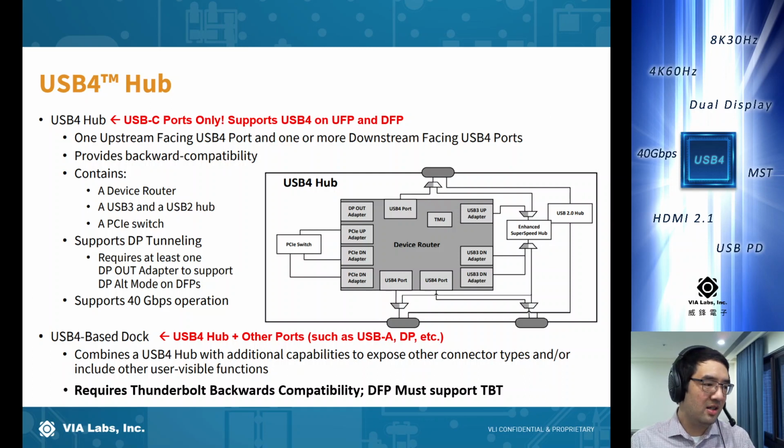Although dock may be kind of a colloquial term and it's been in use for maybe the last 10 years or more, when we're talking about it in relation to USB 4, it comes to mean something very specific. You're not allowed to call a USB 4 device a dock unless it meets the spec definition of what a USB 4 dock is. A USB 4 based dock, again, has USB 4 downstream ports. It's required to support Thunderbolt 3 backwards compatibility, and also the downstream ports have to support Thunderbolt 3 as well.